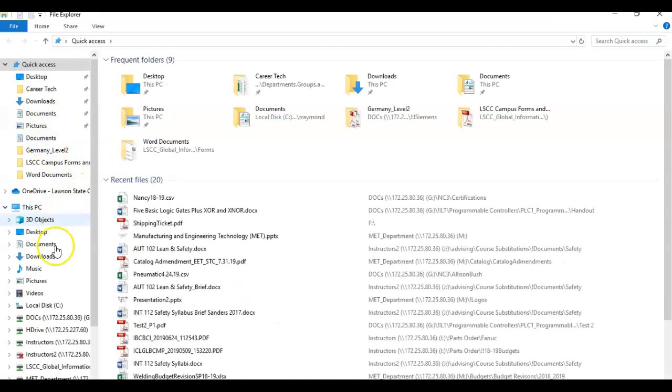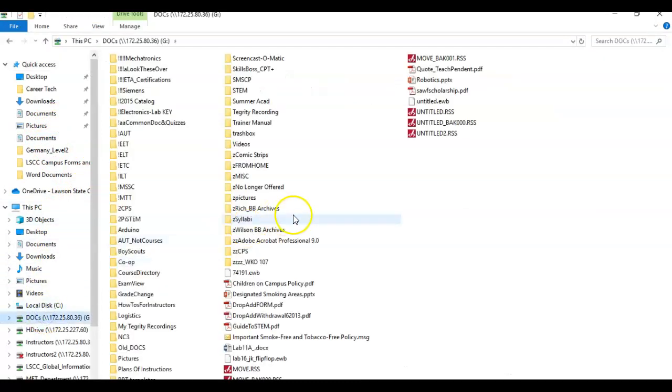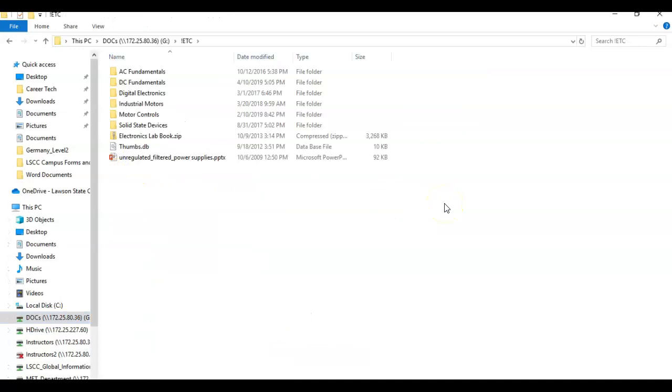So everybody have a pretty good idea of saturation, cutoff, and active? Saturation, it acts like a what? And how much voltage will it drop? A little over, right? Because it's not a closed switch. Around 100 millivolts, right around there. Then when it's cut off, it acts like a what? Open switch.